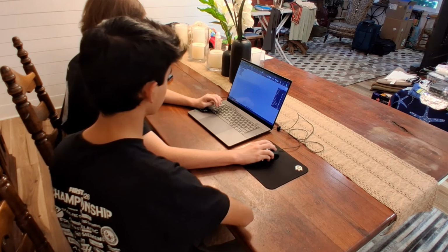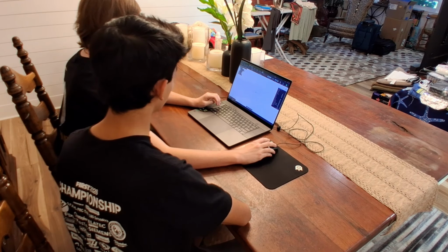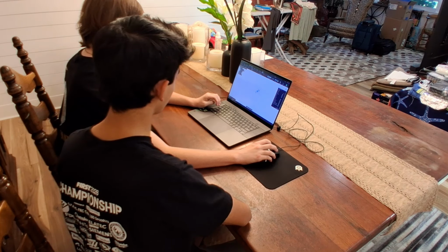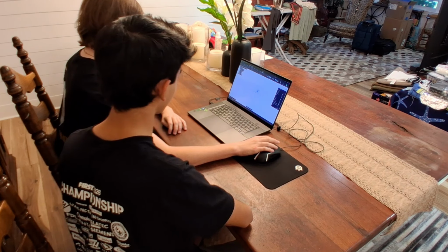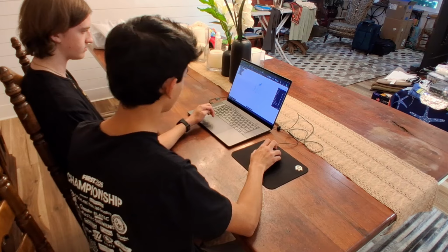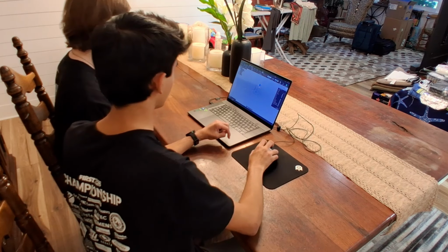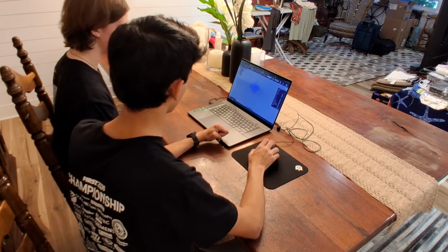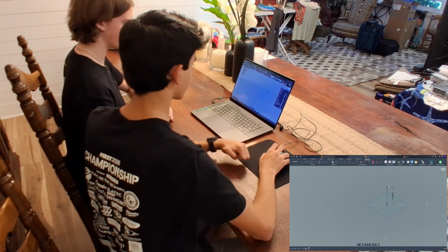Yep, so now you come back, make a line going up vertically from the center point. Yep, so just take your line tool, go up, and then make sure you paste in that distance, right? Alright, nice job. Yep, there we go. As you can see, you made a line going up. So now when we do our loft, that's going to give us the right edge line.